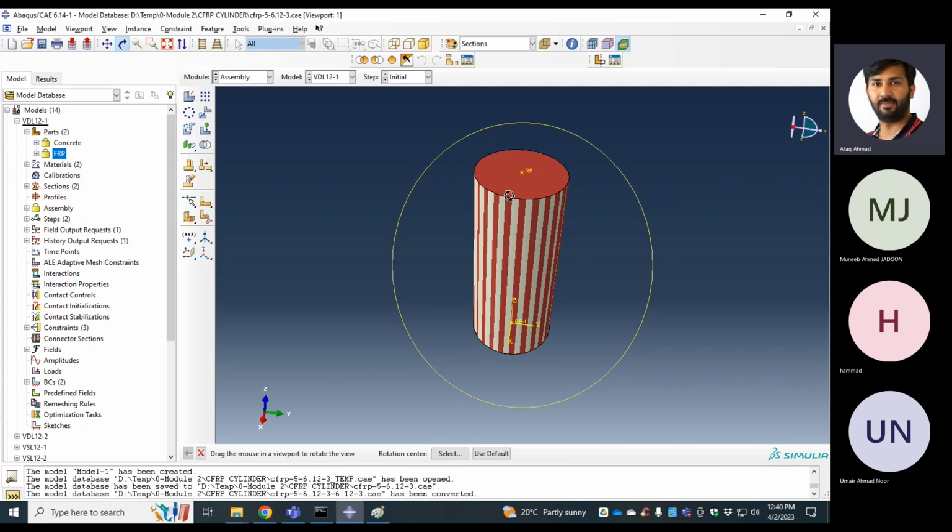Normally we have circular bridge piers due to their versatile nature of resisting the load in different X and Y directions during seismic zoning. So we use circular members instead of rectangular ones. And then you apply a steel jacketing, the hollow steel casing, or the CFRP around it. So that's the problem.